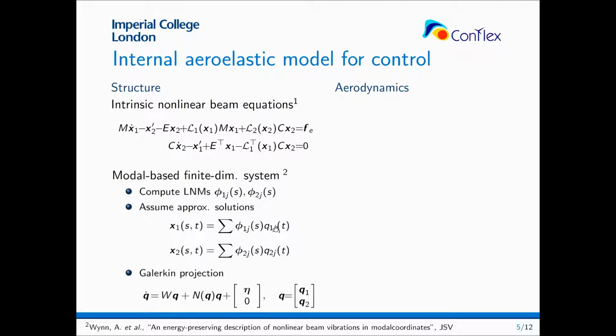And by a Galerkin projection, we finally obtain this low order ODE, ordinary differential equation, in terms of the temporal coefficients, where we see that the nonlinearities inherent in the systems are retained.